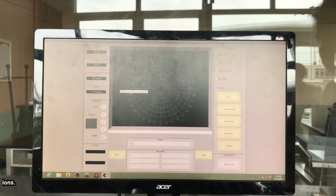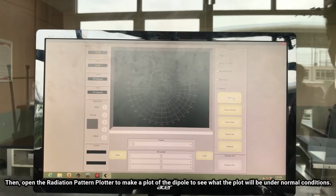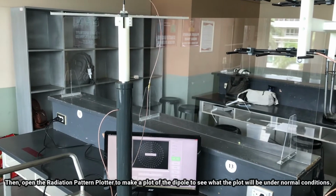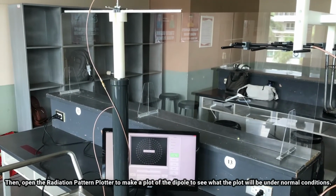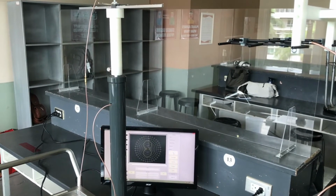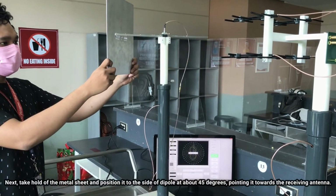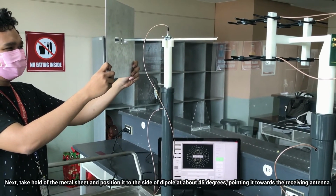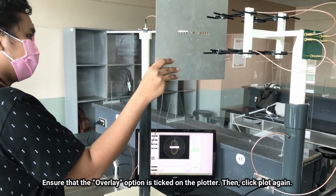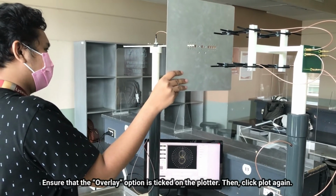Then open the radiation pattern plotter to make a plot of the dipole to see what the plot will be under normal conditions. Next, take hold of the metal sheet and position it to the side of the dipole at about 45 degrees, pointing it towards the receiving antenna. Ensure that the overlay option is ticked on the plotter, then click Plot again.